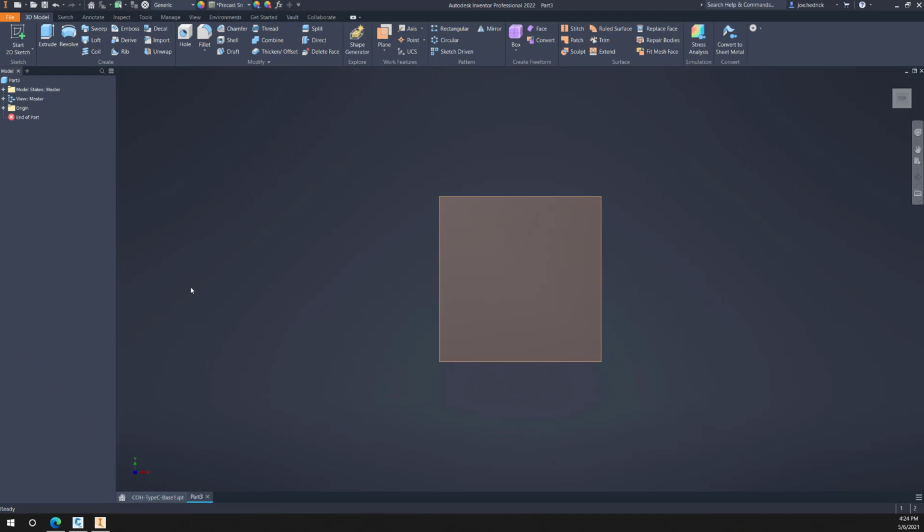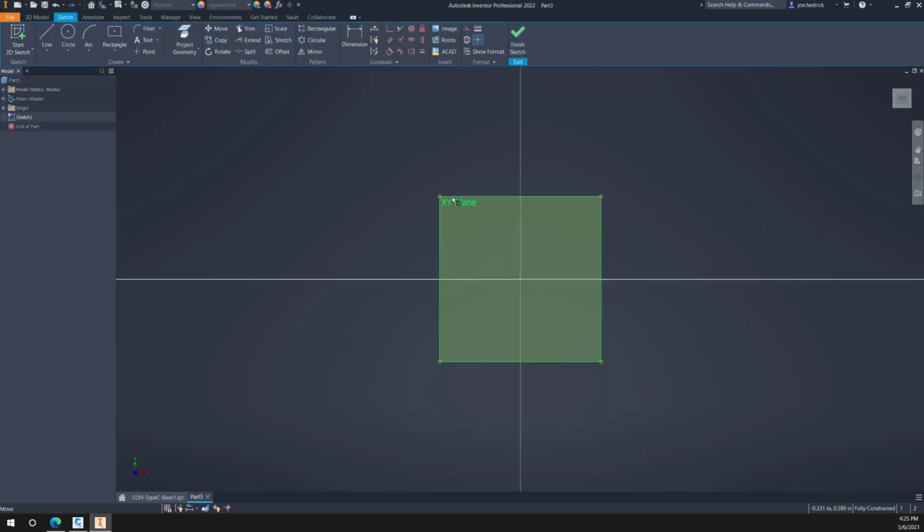All right, back in Inventor with a new part started from my template. Let's go ahead and model the surface structure really quickly. And again, this is going to be kind of variations on the same theme. It's somewhat repetitious. We're going to start with our plane. I'm going to have to start a sketch, attach it to that plane. Let's draw a rectangle.